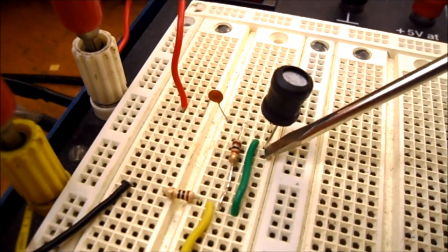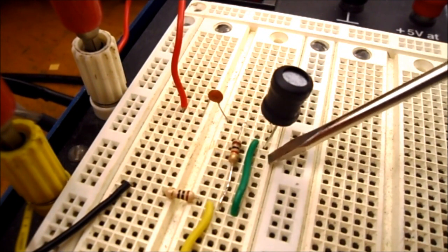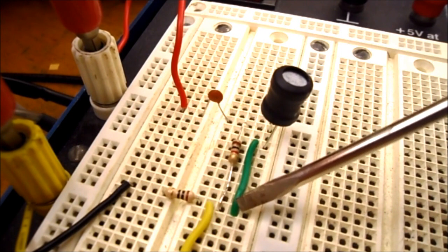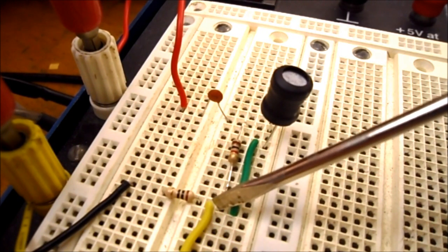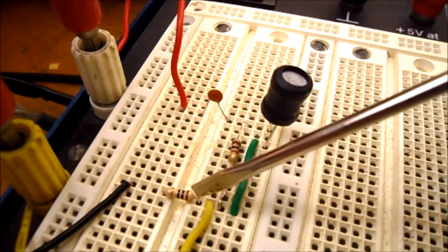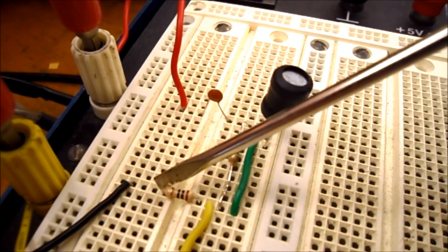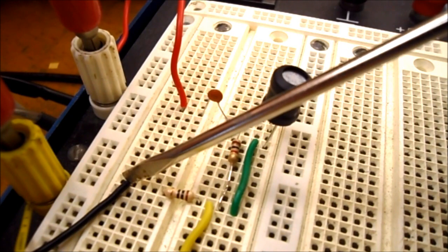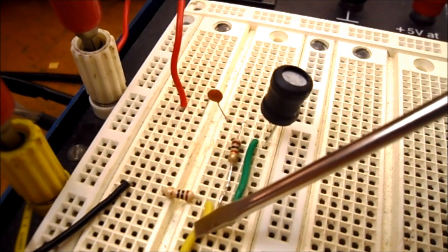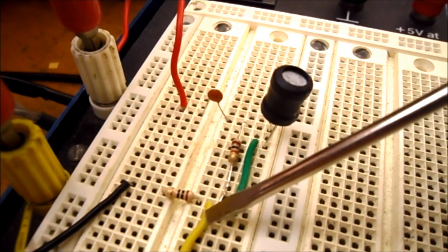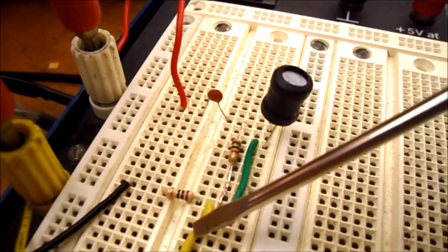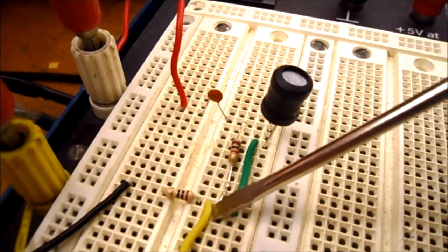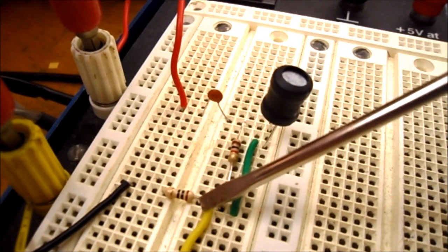On the other side of the inductor, I have a jumper wire, because if you spread the inductor legs too far apart, they will break off the inductor. So at the bottom, my inductor does join back to the 1 k ohm resistor and also goes to the 10 ohm sensing resistor. The other side of the 10 ohm sensing resistor goes back to the common of the function generator. Right now I have a red lead from the oscilloscope channel 2 joining to the yellow lead here that's going across the 10 ohm sensing resistor.